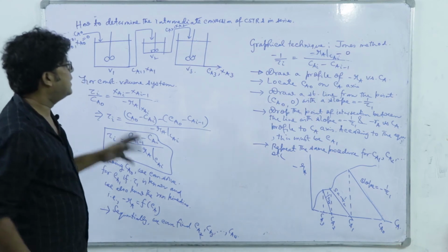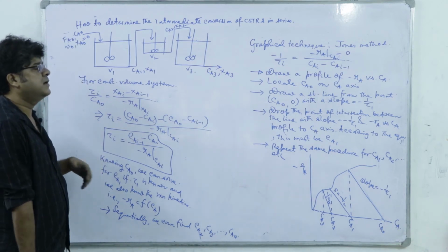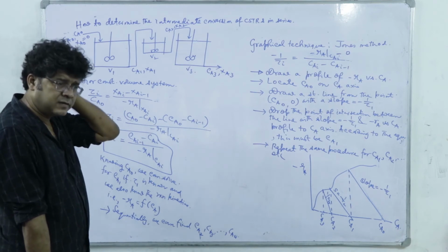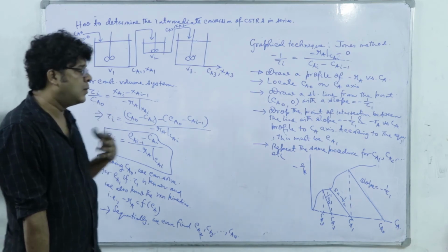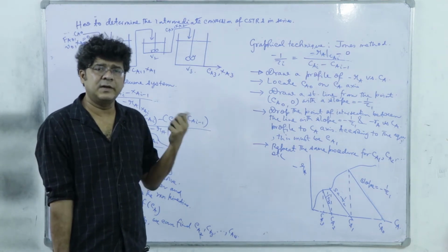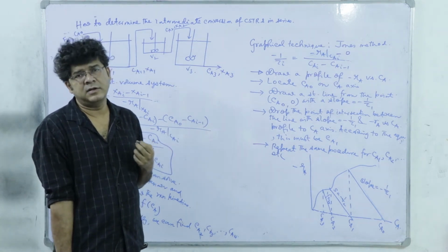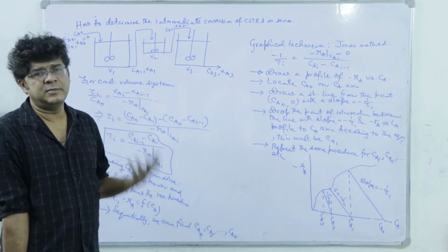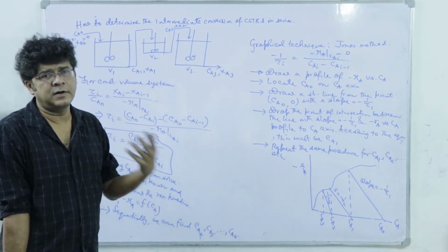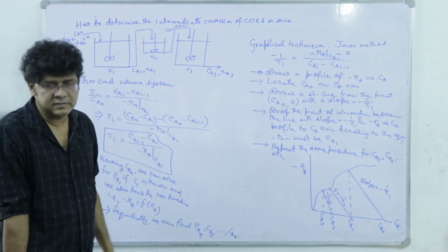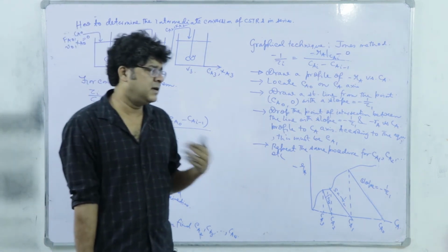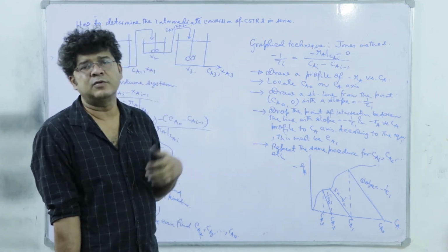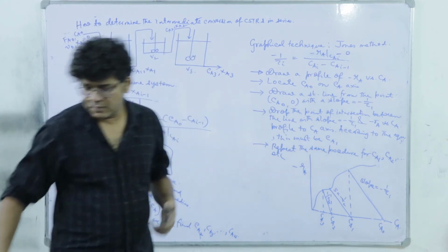So next our question will be, if I have 2 CSTRs or 3 CSTRs, what should be the optimal sequence of their series connection? Like whether we will go for the smallest, then the intermediate, then the largest, or largest followed by the intermediate followed by the smallest. What is the rule or what should be the formalism to decide about the sequence, right.